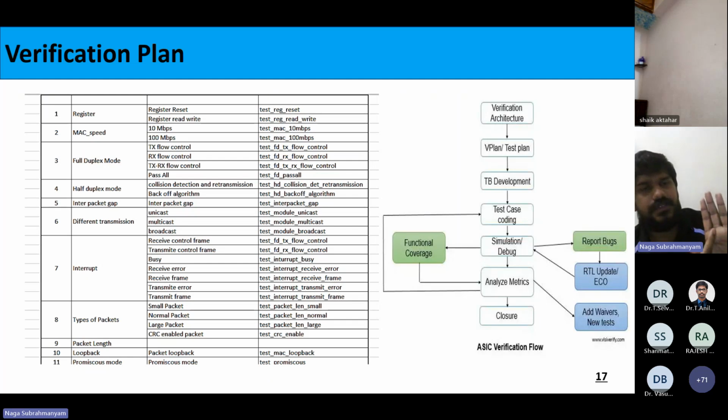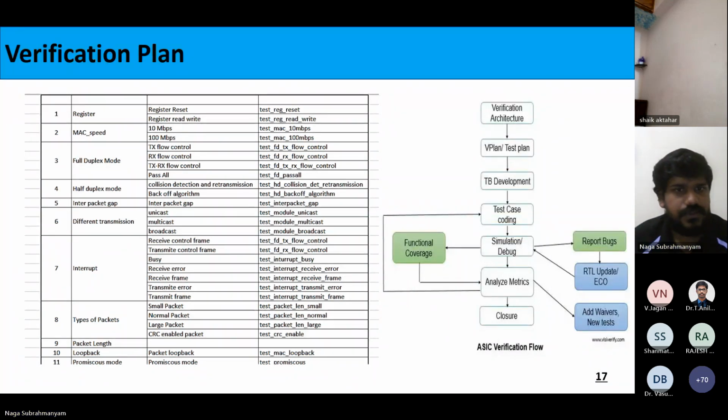If I write something into a register, this register is connected to the control flow, meaning the state machine. The state machine will change according to the register value and enable the data flow logic. Nowadays most designs are like this, because this is a comfortable way of doing things and it is effective also.